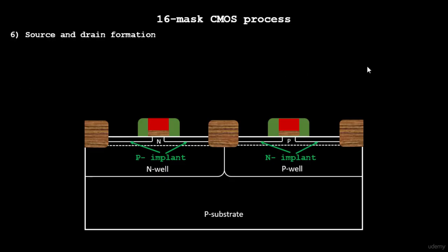Hello everyone, let's continue our discussion with the LDD, or lightly doped drain, formation. What we want to exactly achieve over here is this doping profile. The doping profile we try to attain is P plus, P minus, N. What do you mean by this? This is your N well where we are trying to fabricate the PMOS. In case of a PMOS, you have source and drain, and source and drain are both P type. So that's this one, P plus, the P plus doping profile which is coming over here. P minus is the lightly doped drain formation, or the LDD, that we are trying to bring up now, and N is what you already have. So this is the kind of source-drain profile that we're trying to see over here.